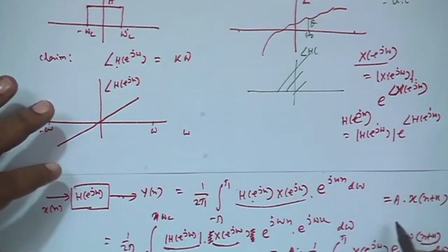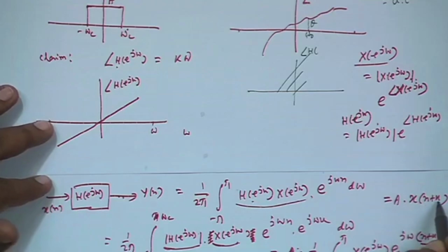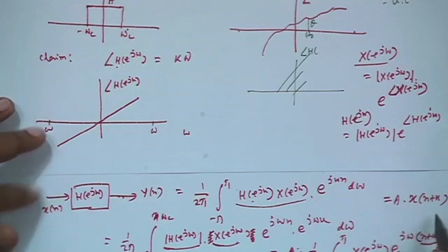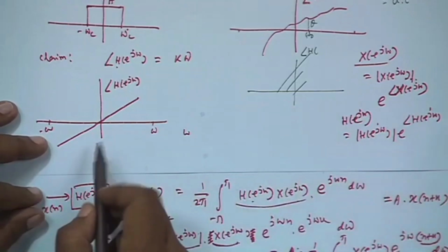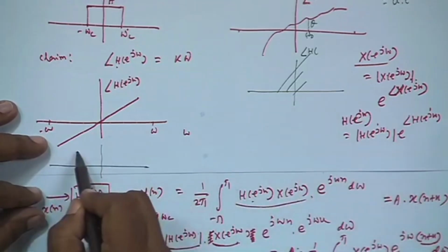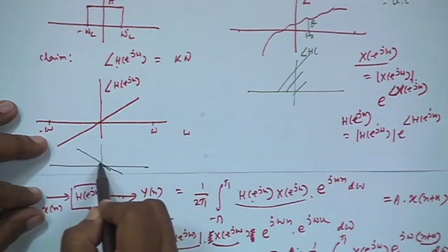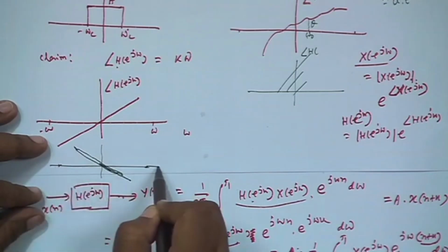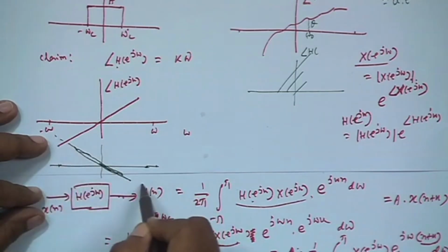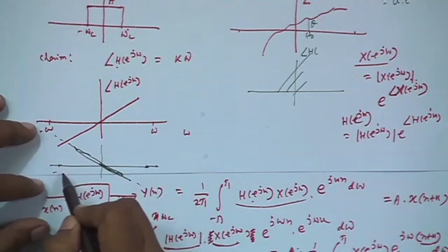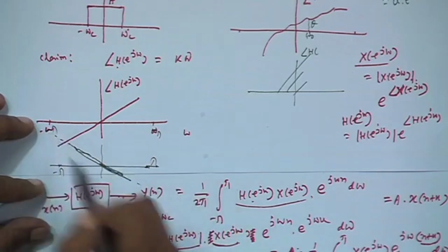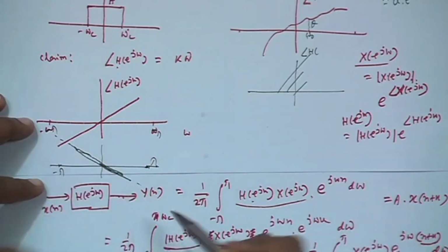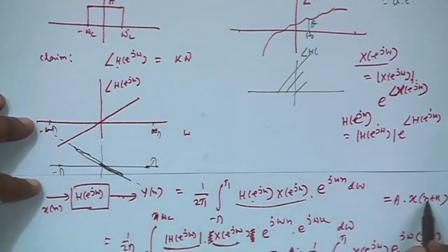Okay. So, you get back x only after a delay. Here the k is positive, but I want the filter to be causal. In that case, k must be negative. So, actually the slope should be, for all causal systems, you will see the phase always goes down like this, from minus omega to omega, or from minus pi to pi you can take. Okay. K should be negative.